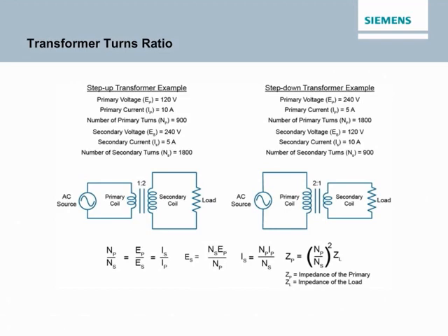Transformers are rated for the amount of apparent power they can provide. Because values of apparent power are often large, the transformer rating is frequently given in kVA, kilovolt amperes. The kVA rating identifies the current and voltage a transformer can deliver to its load without overheating.